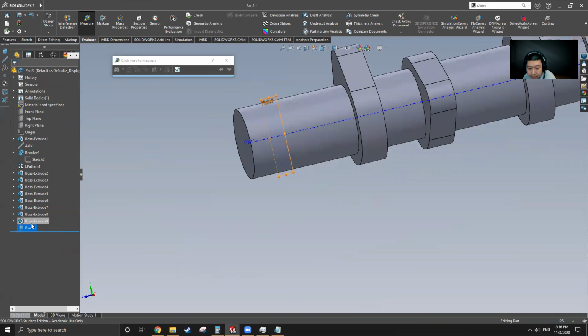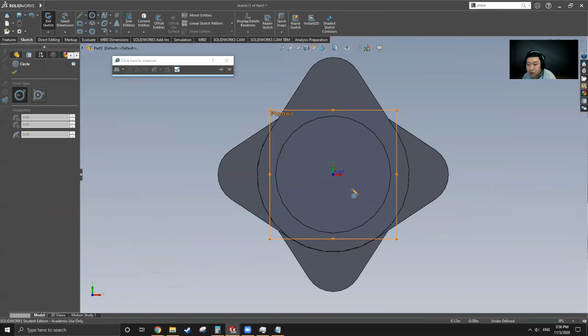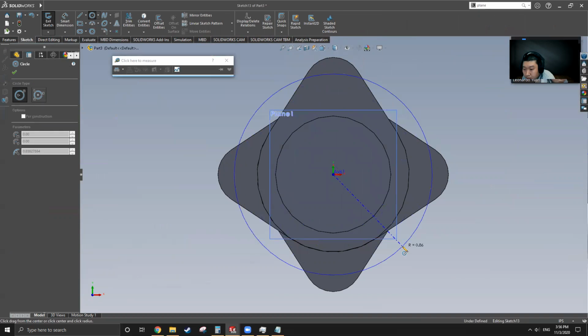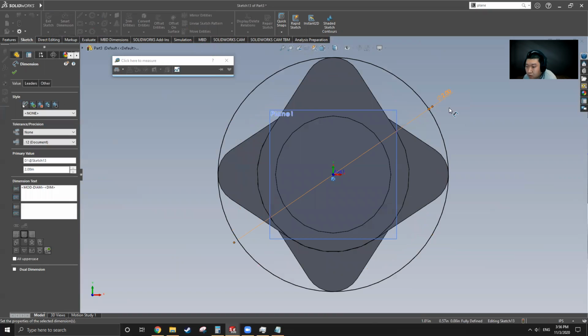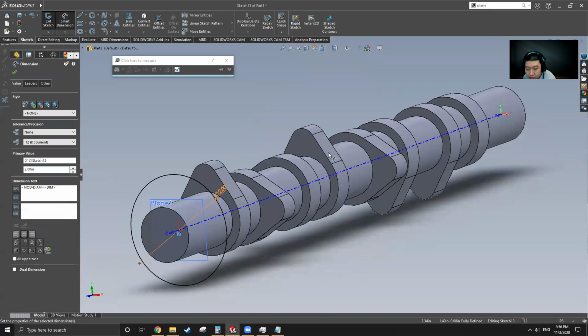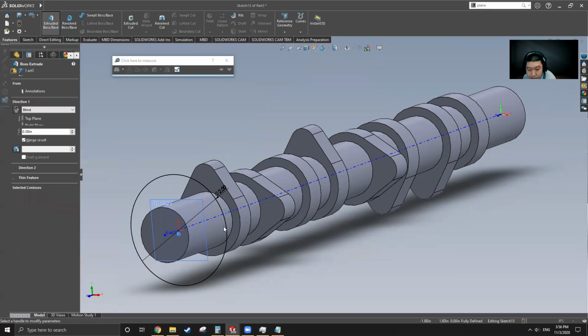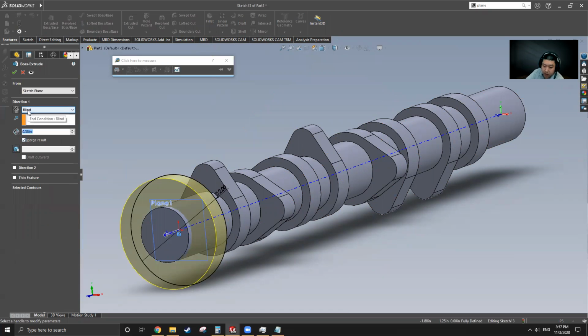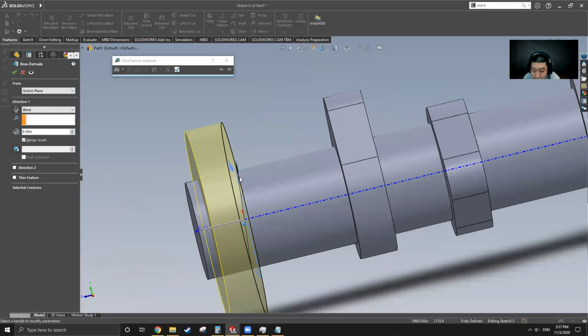Okay, so we can select this plane and start drawing a circle from origin, it's gonna be 2 inch in diameter. Okay, so the circle is drawn on this plane, and let's extrude this. So be careful right here, since we want the middle of this disk sitting on this plane.